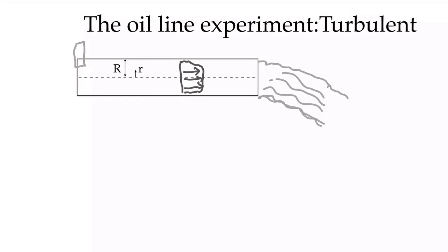And as the flow rate decreases, the Reynolds number goes down, and when it gets below 2300, it will relaminarize, and you'll see the laminar flow solution again. And then the resistance will go down, and the flow rate will start to increase, and you can get a situation where it's going back and forth between a laminar and a turbulent solution. And so you can have laminar and turbulent flow at exactly the same Reynolds numbers, and you often have these transitional flows where it's spending some time in the turbulent regime and some time in the laminar regime, and very often this has to do with the fact that the resistance is changing, and therefore the flow rate is slightly changing, and we're going back and forth between laminar and turbulent flows.